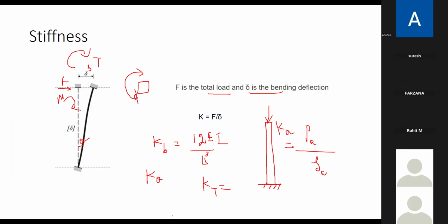But in case of seismic, we are going to consider that the degree of freedom is only in this axis, the x-axis. We will not worry about all the other stuff. Of course, ETABS will consider everything and mode shapes will be developed. But our code formulas, the equivalent lateral load method, and even the response spectrum given in the code are only for the x-axis.